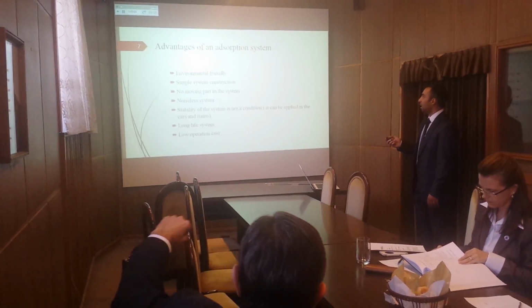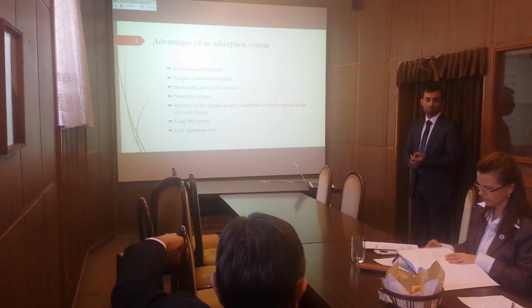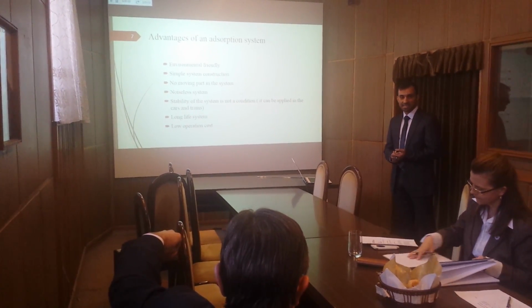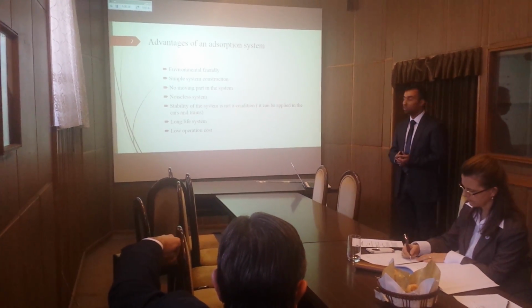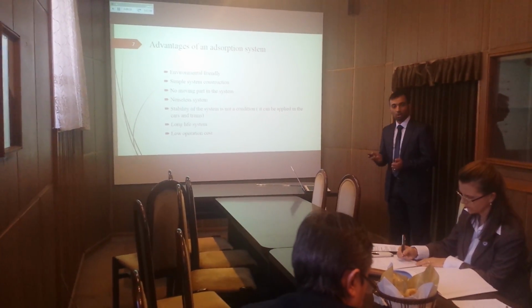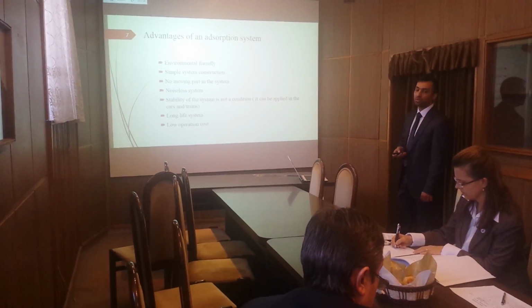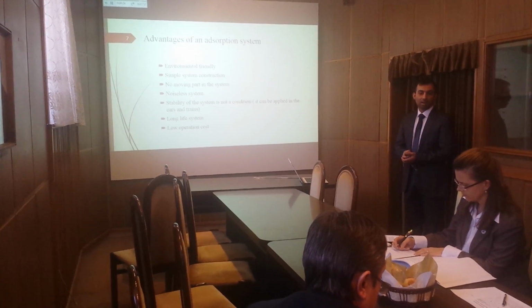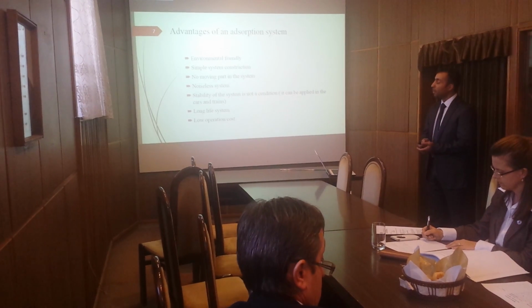The advantage of the absorption system is that it is environmentally friendly. There is no moving part in the system. It is a noiseless system, it has a long life, and also low operation cost. And also it is suitable to apply to trains and cars, because stability is not a condition in these systems.